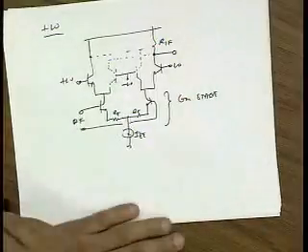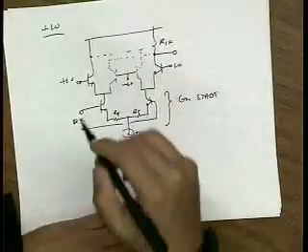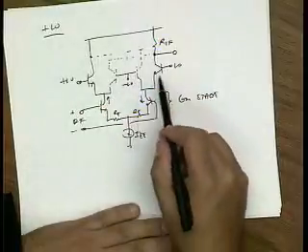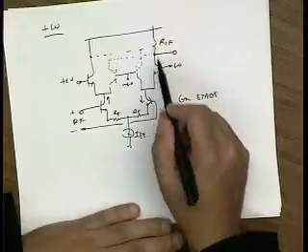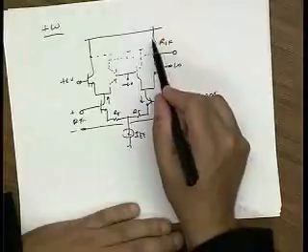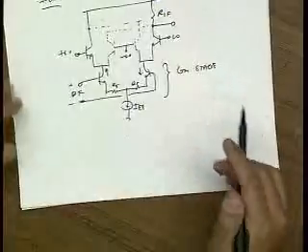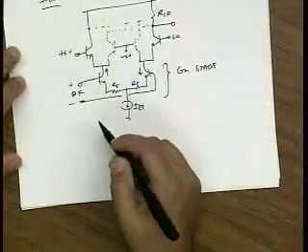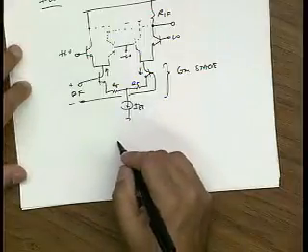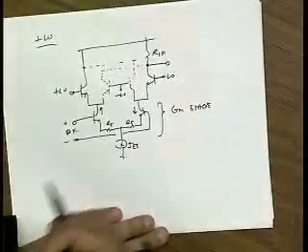Okay? So I'm assuming extremely hard switching. And so you could see that the differential current flows to the output with a certain value of gain. In the limit that this is very hard switched, all the current goes to the output, so the gain would be, let's say in this case, plus 1. Let me draw now also what happens during the negative LO cycle. Well, I guess I don't need to draw it. You guys can see what happens.